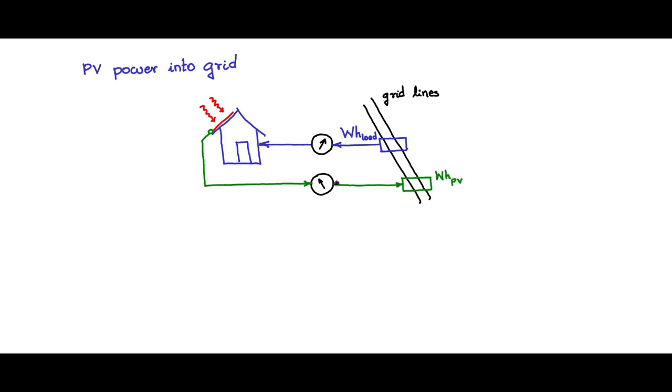Now that we are putting back the energy, let us say we have a requirement that we need to have a net balance, that is, a zero net energy that we need to incorporate into this design. In most of the states, most of the places, you will have a tariff for the watt hours that we are drawing from the line, and the tariff for the watt hours from the solar energy that we are putting into the grid is different, generally higher.